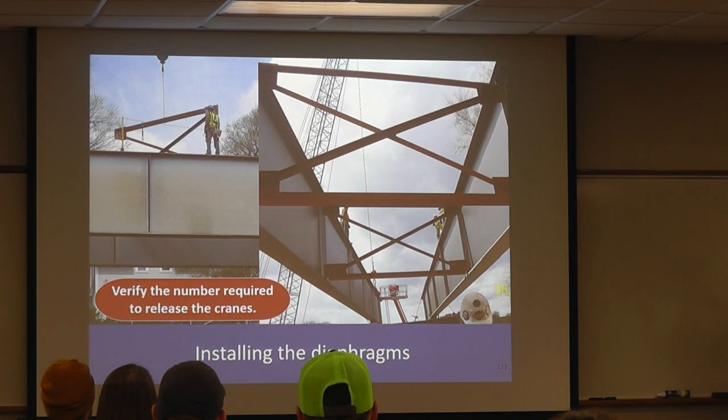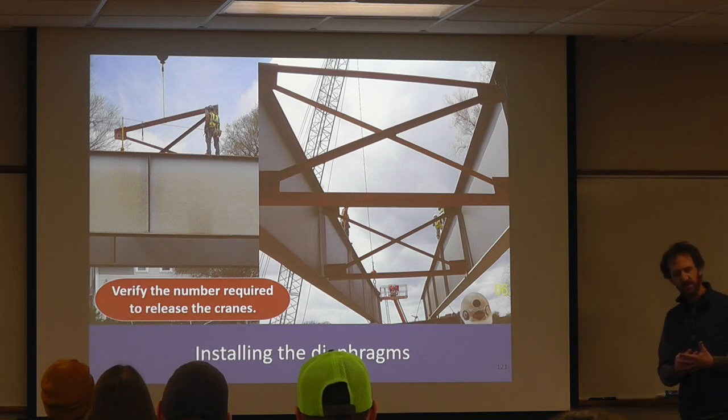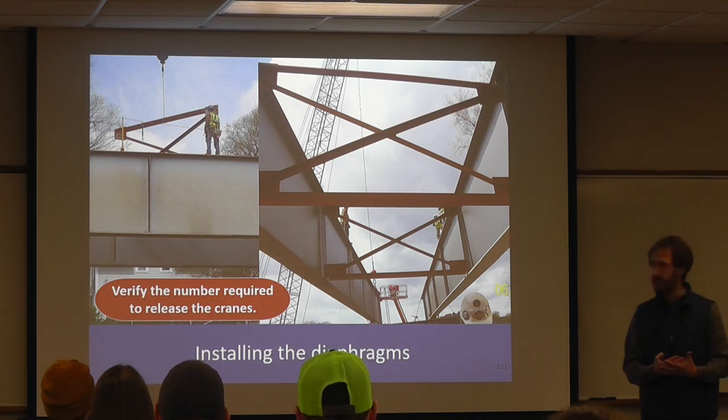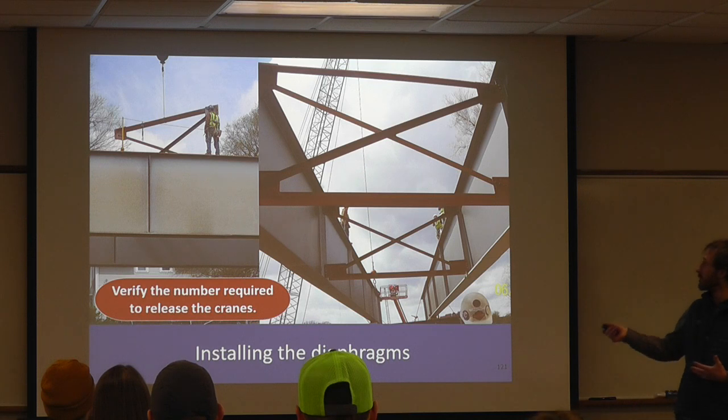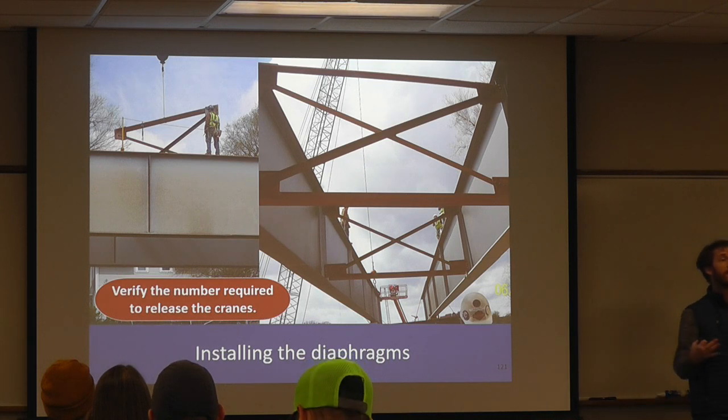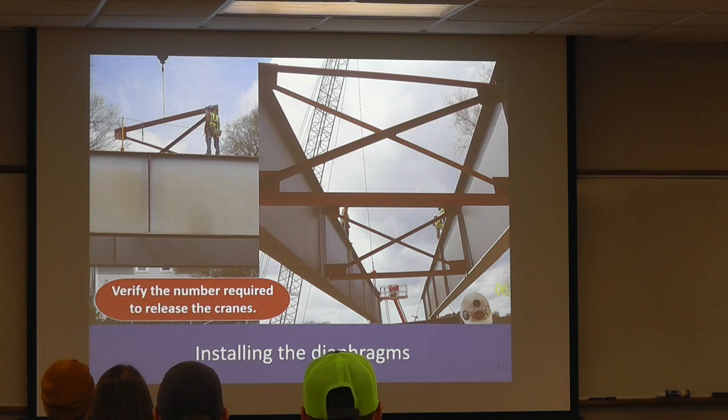The pins are used to ensure geometric control. We're going to dive way into that coming here. Get your field splices installed with the appropriate number of bolts and pins. We're going to go in and feed the appropriate number of diaphragms. Within their erection plan, it should tell you how many diaphragms they need to install before they have unhooked the crane.